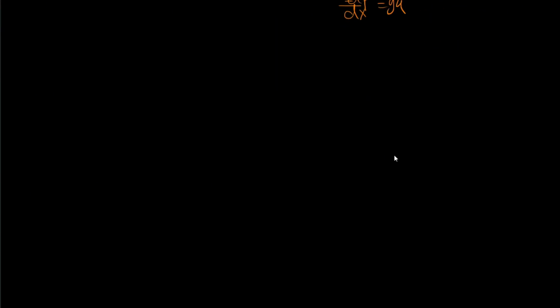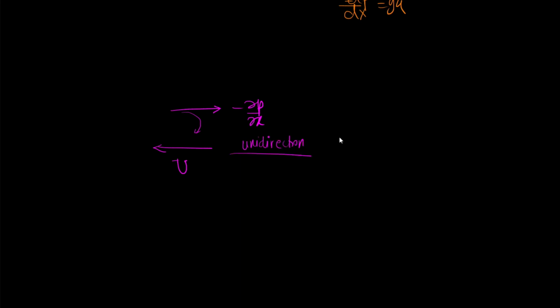On the one end you have a plate being pulled in this direction, on the other end you are trying to push fluid in the other direction. So it's not always a stable configuration. This is the direction of minus dp dx, this is the direction of U. You can imagine that the fluid is trying to overturn. So the assumption of unidirectional flow need not always be maintained, and it can lead to a flow instability.